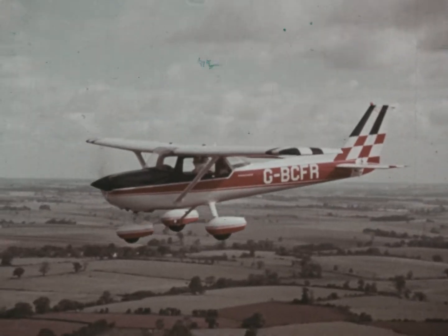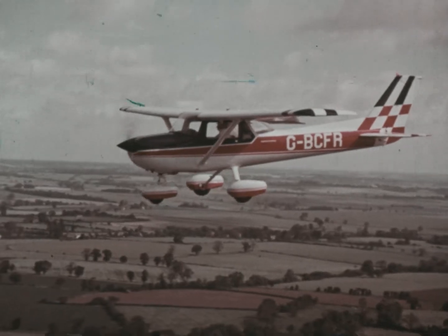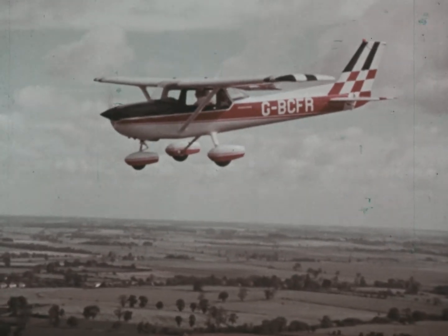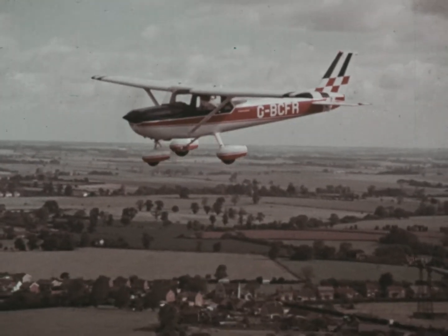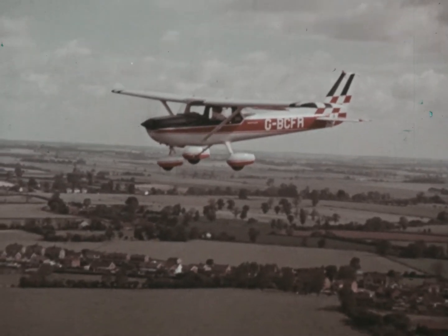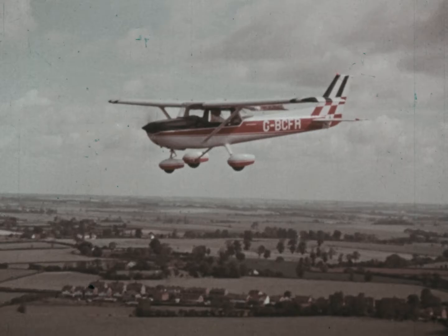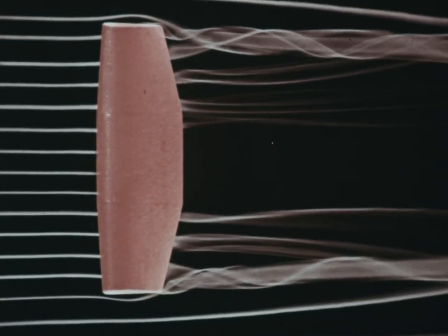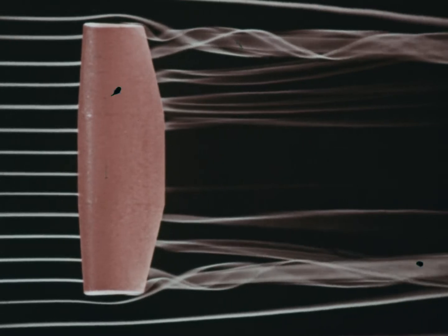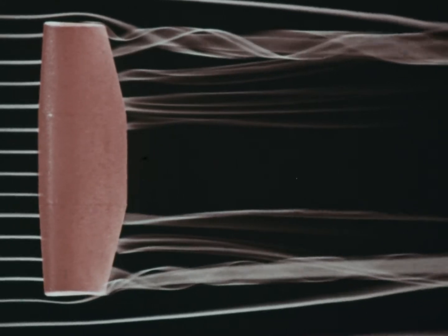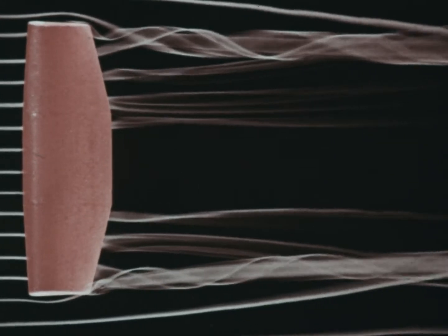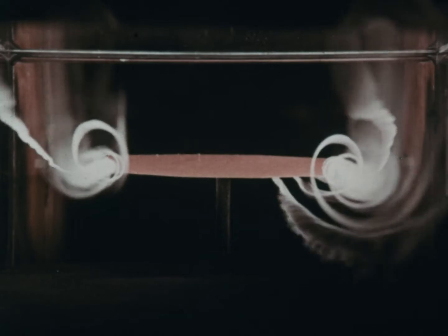A third source of drag increases in inverse proportion to the speed of the airplane, at its greatest when the speed is lowest. We call this induced drag, or trailing vortex drag, and it arises from lift. As a result of the pressure difference between the upper and lower surfaces of the wing, air tends to spill over the wingtips from the area of higher pressure below the wing into that of lower pressure above the wing. The two airstreams meeting just above the wingtip form vortices, a corkscrew pattern of twisting air that produces a considerable amount of drag.